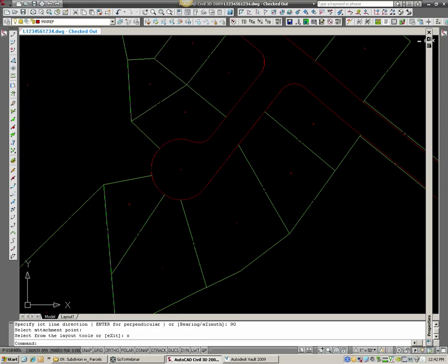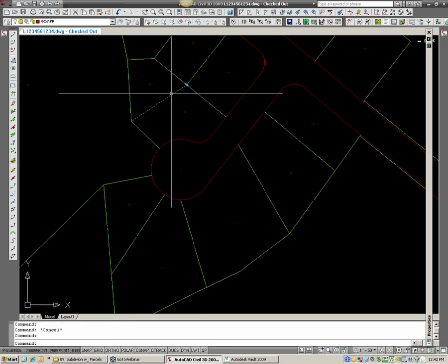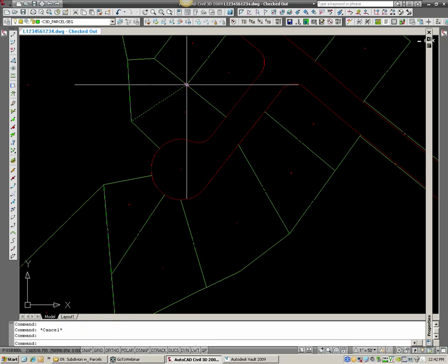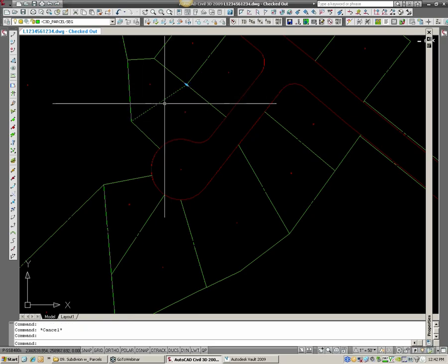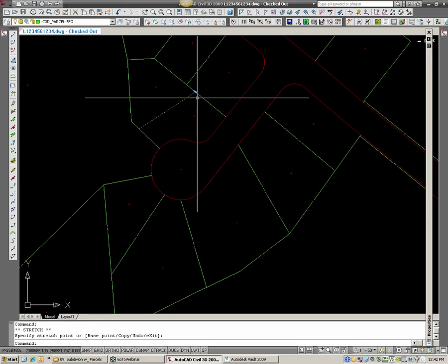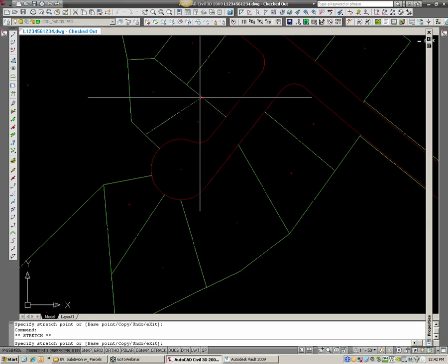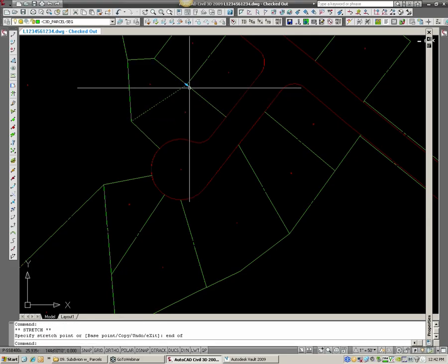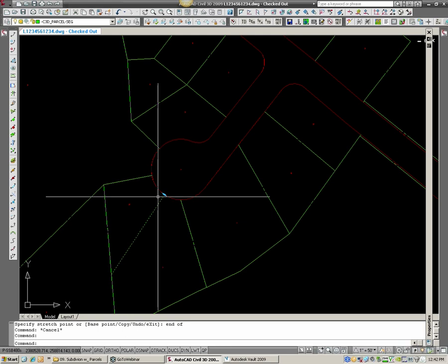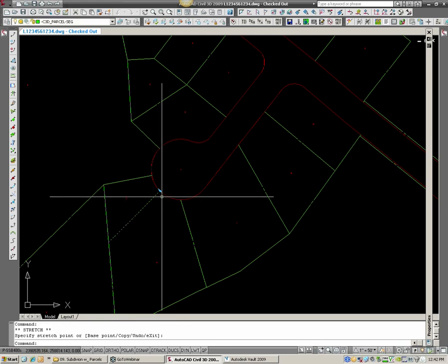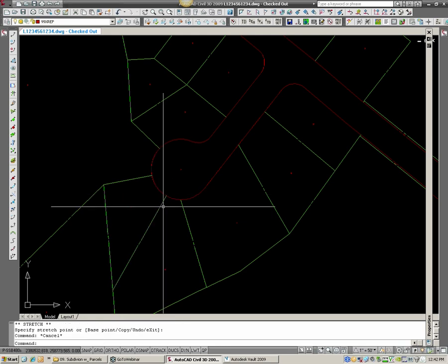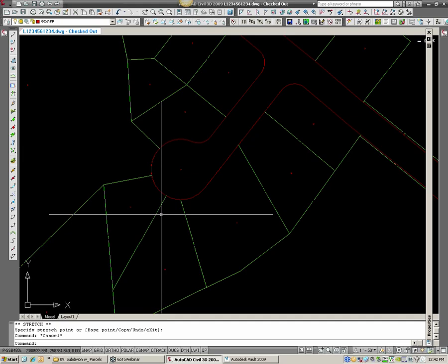What's great about this freeform create is the way the tools are editable. So now this line is defined by azimuth, so if I slide that around, it's going to hold that same azimuth or bearing. This line was defined to come off perpendicular, so it's going to always stay perpendicular. I think to me, that's the best tool in the toolbox for creating parcels.